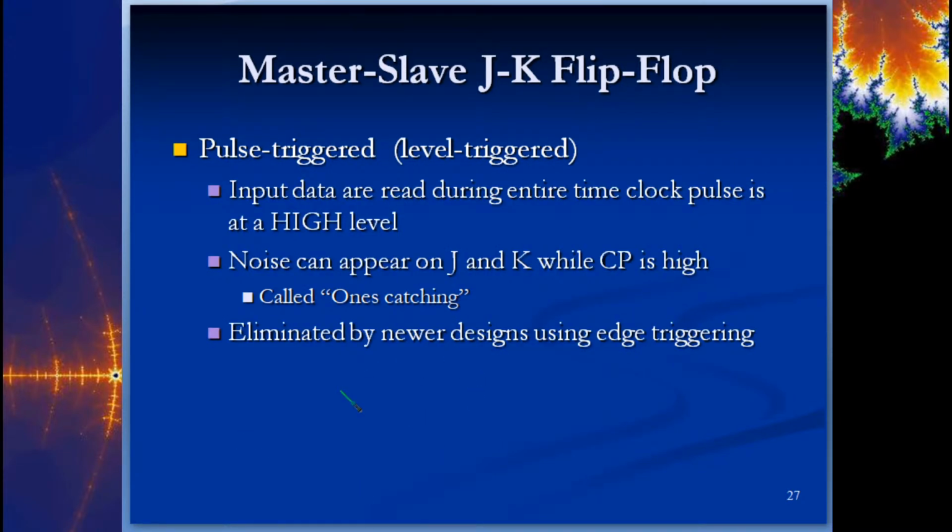So if that clock pulse is what we call pulse triggered or level triggered, which you may or may not see on a quiz, that is, the input data is going to be read the entire time that the clock pulse is at a high level. Okay, so here's a problem with that: we have what's called a ones catching error.